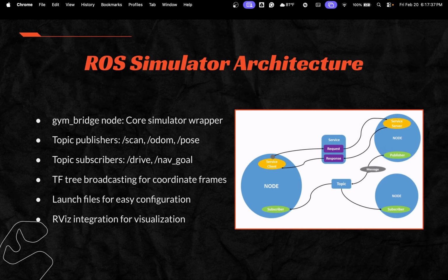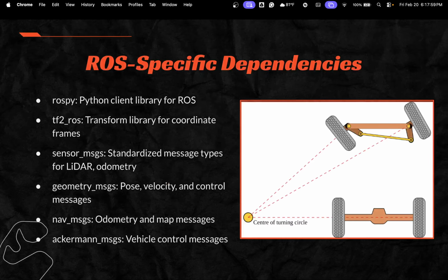Just like I mentioned before with ROS, the main things are nodes. You have nodes and they communicate through topics, named buses in a way. A node can subscribe to a topic or publish to a topic. That's how they communicate, and all of the nodes together make the entire system. Another thing you should probably know is that our vehicle's steering is based on something called Ackermann steering, which is pretty simple.